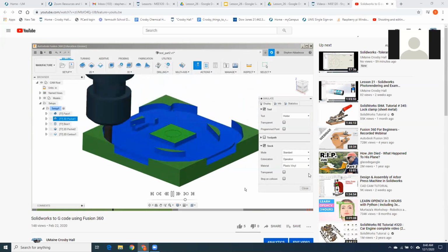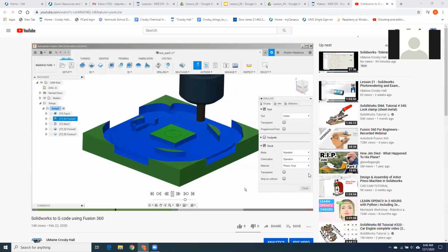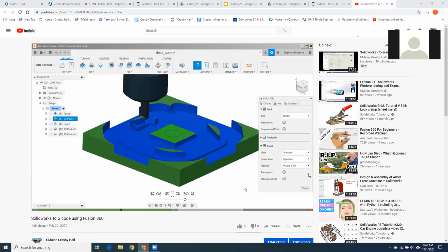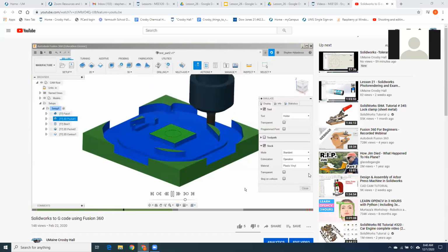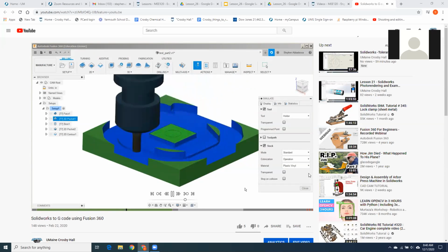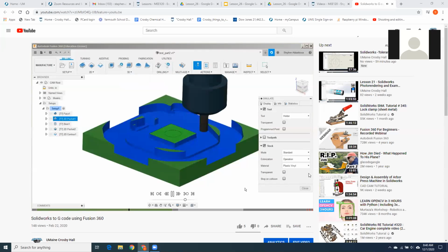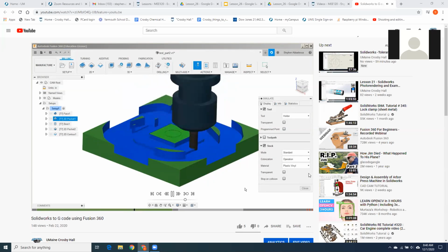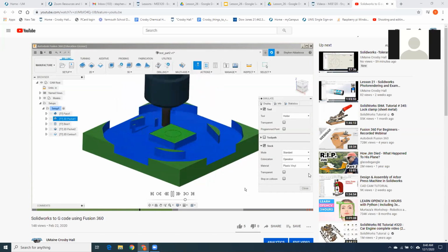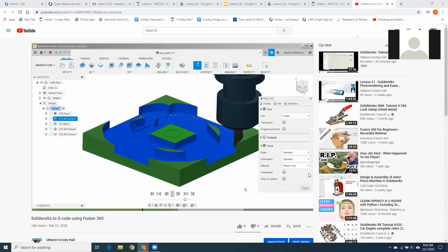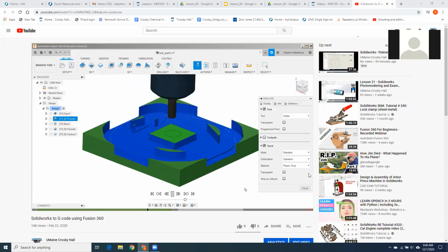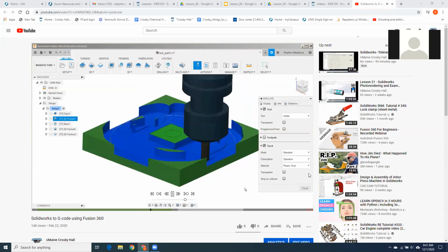And go down another cut. Again, you do not want to take off all the material at one time. Do nice gentle cuts, and that will give you a much better surface finish and it will be much more gentle on the cutting tool. Okay, you can see the edges come into view. We're on our last step down.